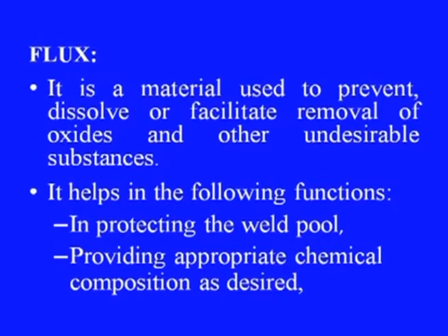Number 1, it protects the weld pool from the oxidizing agents or the oxidizing environment. It provides appropriate chemical composition as desired. Then it helps in improving the properties by alloying materials appropriately. That means, we can add a few materials through the use of flux also.